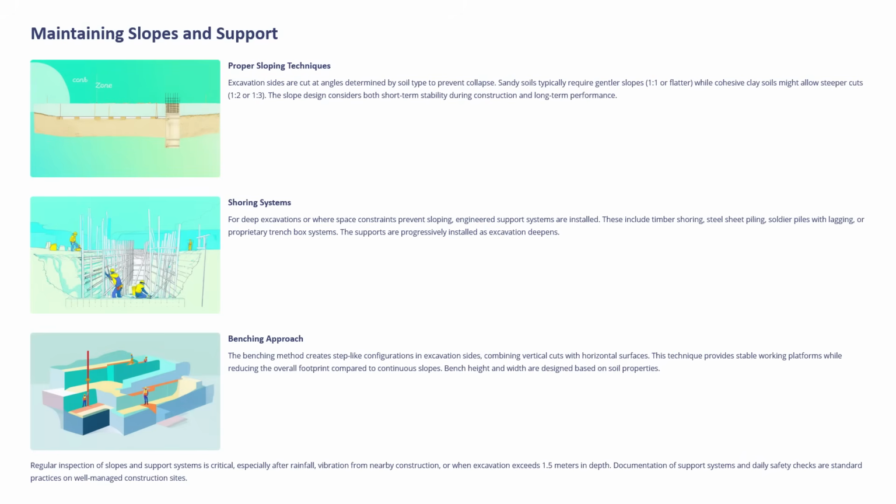Maintaining slope and support is most important while you do digging for the foundation excavation. Proper sloping techniques must be used. Excavation sites are cut at angles determined by soil type to prevent collapse.